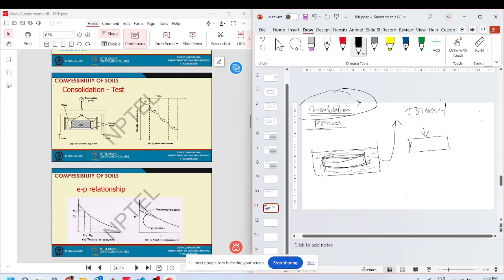But you have to fill the pores with incompressible fluid in order to actually calculate the compressibility of the matrix. If you don't fill the voids, it will just compress, because the air is too compressible.